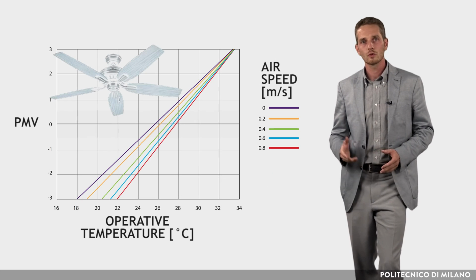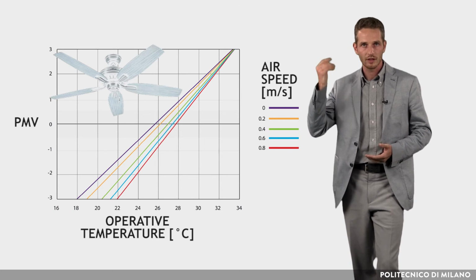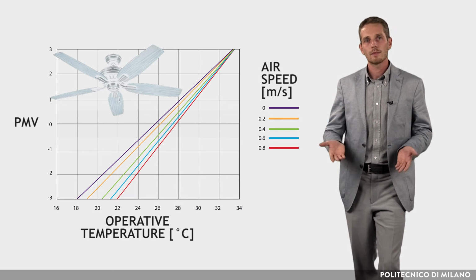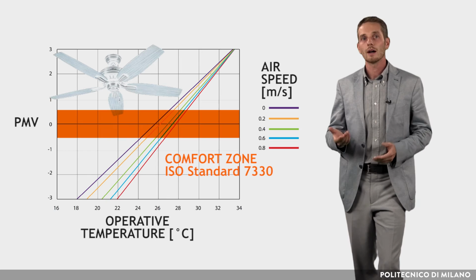In an urban environment, it is very often not possible to keep the windows open for natural ventilation. Consequently, even in those periods when the outside air temperature is such that, with adequate ventilation, the air conditioning should not be needed, it becomes necessary to use it. In these cases, or in spaces with no air conditioning and where air movement is not sufficient, a ceiling fan can be used. It is also useful when used in conjunction with air conditioning, because the increase in air velocity means that the air temperature can be increased with the same comfort level but lower energy consumption.